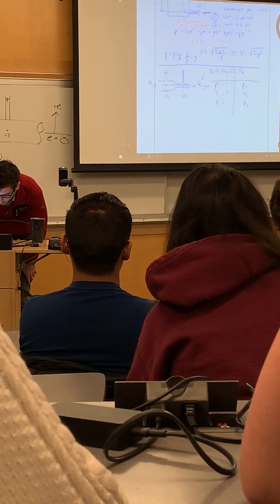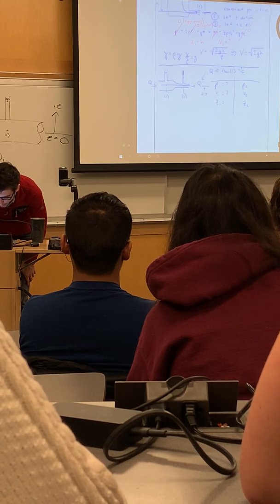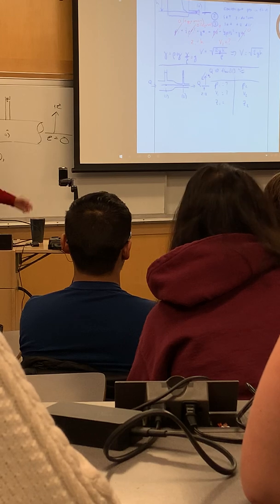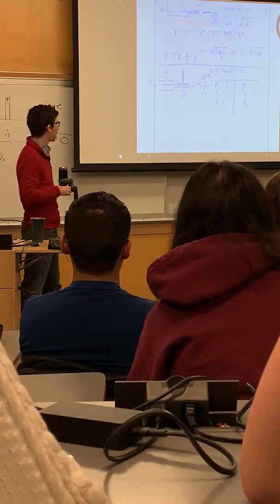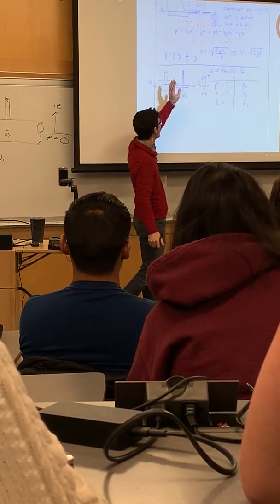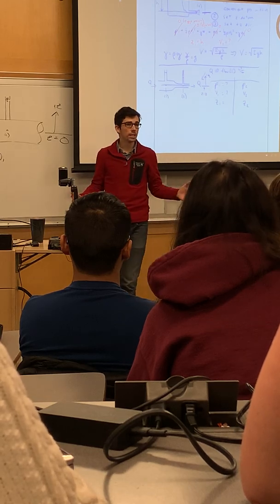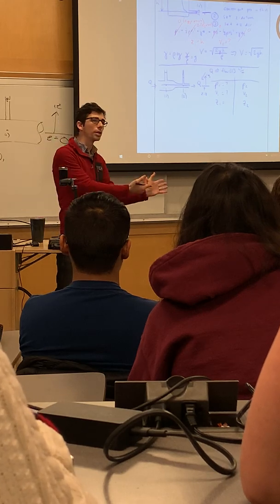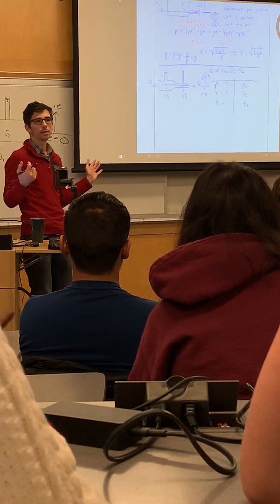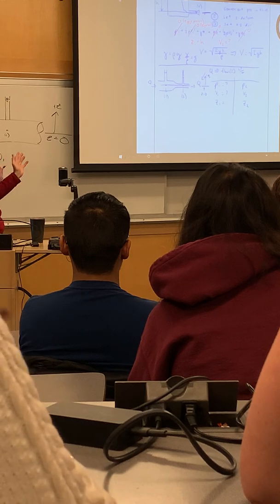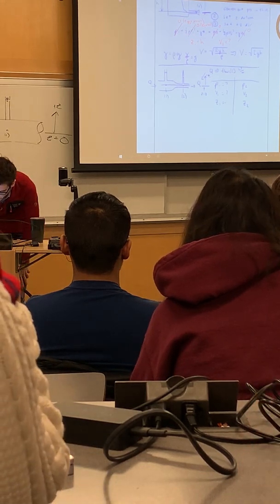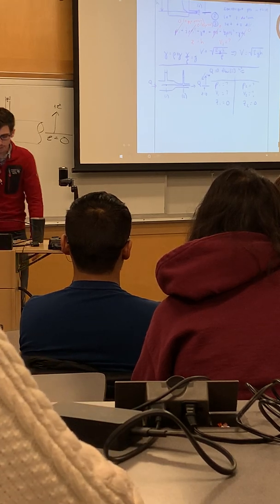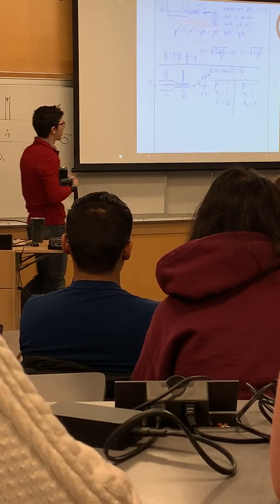We talked about putting our datum right here. Z equals 0, define this as positive Z. Right, yeah, we'll call it 0, it's on our datum. If for whatever reason you put the datum somewhere else, then Z1 would not be explicitly 0, but what's important about Bernoulli is what's changing from point 1 to point 2. In that case, Z1 and Z2 would have the same value, you'd end up with the same endpoint, right? So Z1 and Z2 are 0. In this case, we have the same thing occurring at point 2 where we have static pressure and velocity.